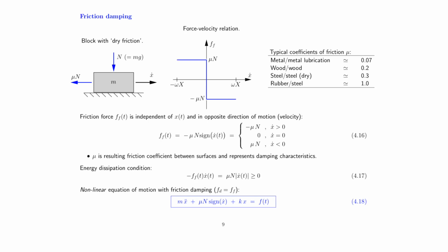That's what we refer to as friction. Friction is not just friction, there are many types of friction. So we're going to consider the simplest idealized friction model, the so-called dry friction or Coulomb friction. So the idea is that we have a mass and we will slide that by a constant velocity, and above some threshold value we will have a constant restoring force that is independent of the magnitude of the velocity. So such a friction force is commonly decomposed into two things.